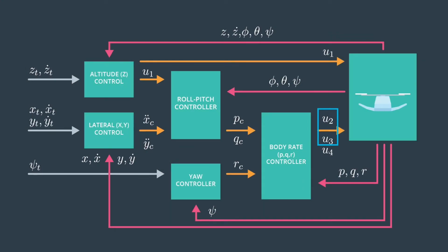The pink lines are the feedback coming from the sensors through the Kalman filter, while the gray lines are the input target location and orientation. Together with the pink lines, they go through each block and produce the yellow output lines. These blocks together give out the required values of forces that each motor needs to get to the required destination.